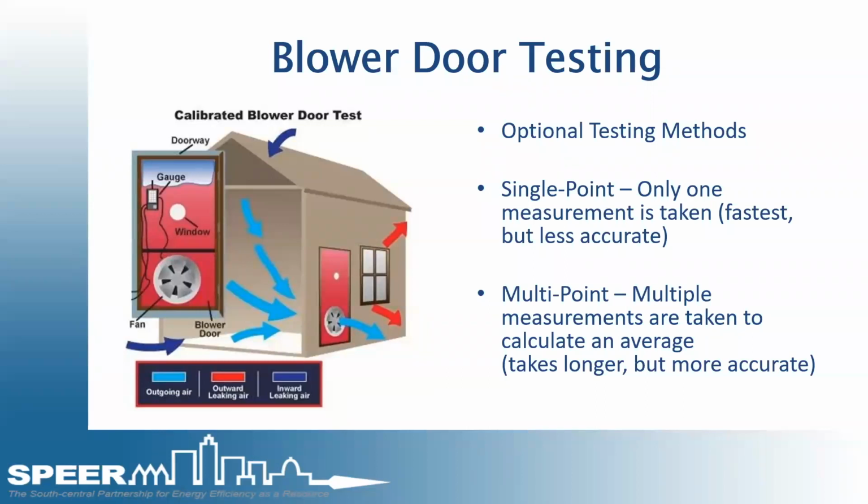But contrary to popular belief, a lot of people think the blower door can pinpoint where problems are. That's not what a blower door does. A blower door measures air infiltration throughout the house. It simulates air hitting the house from all sides, multiple directions at the same time. That's not reality. It never really happens. But this is a standard pressure test that has to be done on all new construction to confirm the air barrier is sufficient enough to pass the test. Doesn't pinpoint where it is.